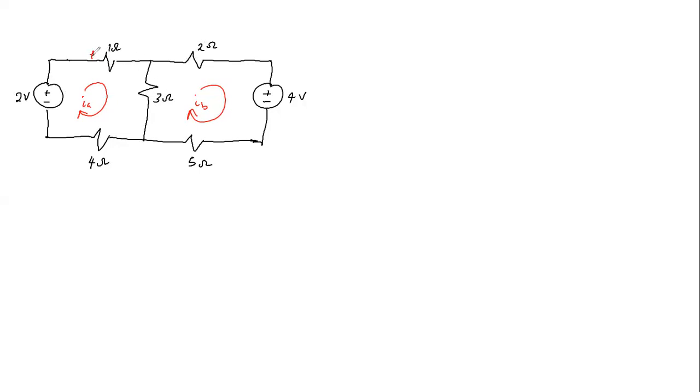So this is positive, current flows in through the positive terminal for passive elements, negative. Then this is the next external, so this is positive, this is negative. Same thing happens here. This is the external here, positive, negative. And this is positive, negative, okay? So the polarities are fixed according to passive sign convention. And then you see that these are the sources we have here.